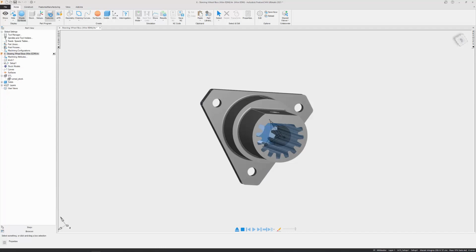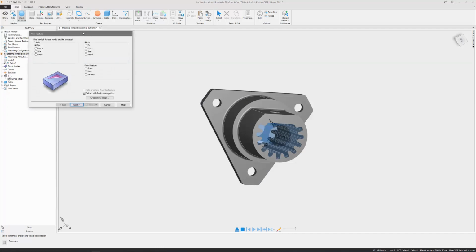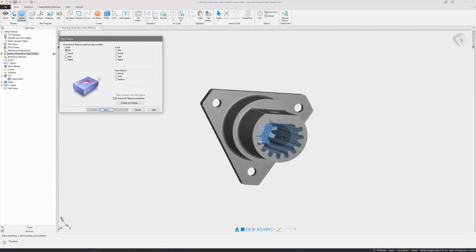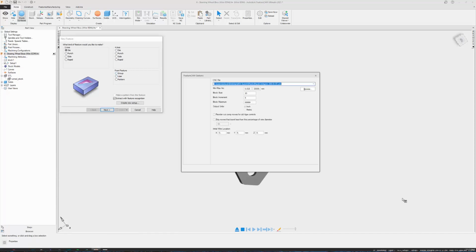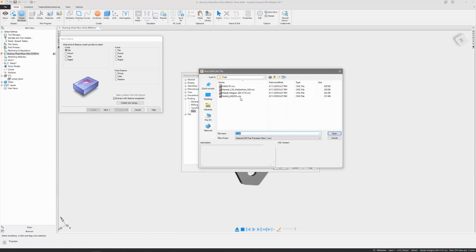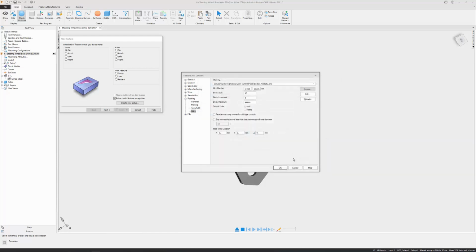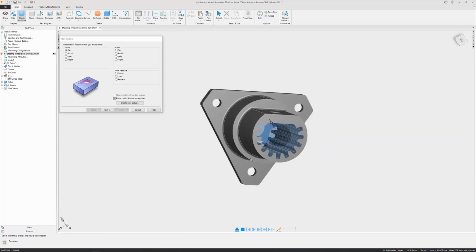So let's just jump straight into it. I'm going to open up the new feature wizard, and because we're in a Wire-EDM document, we're seeing some new feature types here that we haven't seen up to this point. Now this is a 4th axis, didn't mention, and I actually need to grab my post at this point. We're gonna use a SODIC. It's a 4-axis, although we'll just be doing 2-axis Wire-EDM feature here.